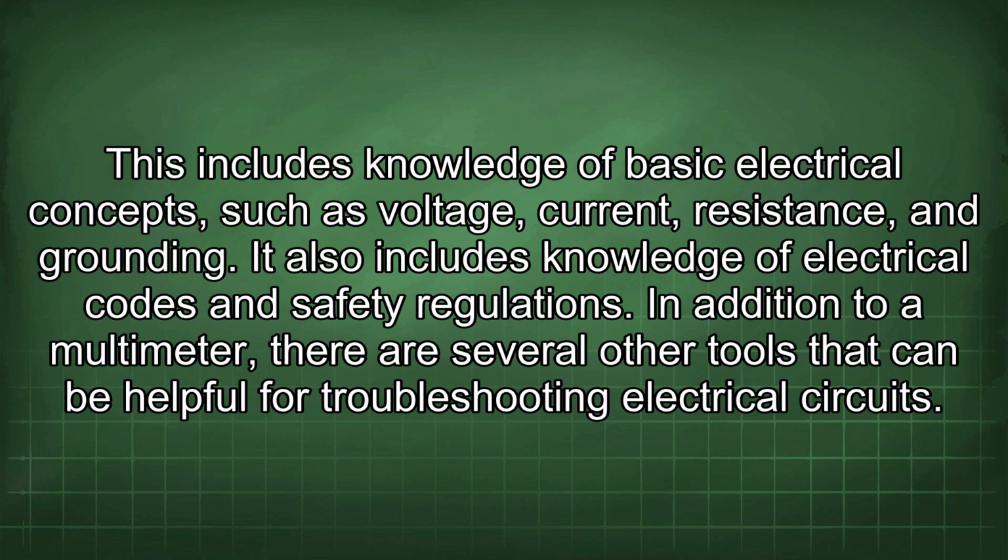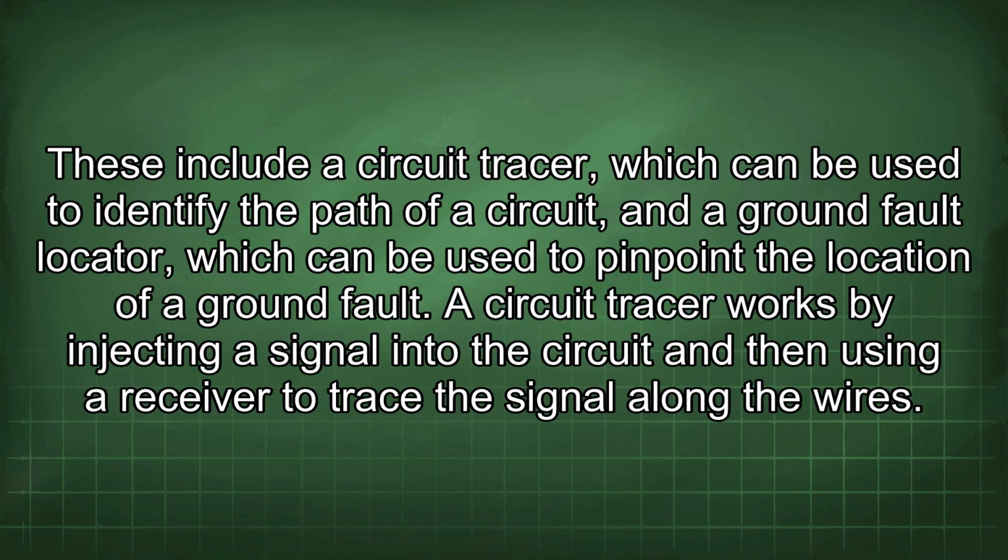In addition to a multimeter, there are several other tools that can be helpful for troubleshooting electrical circuits. These include a circuit tracer, which can be used to identify the path of a circuit, and a ground fault locator, which can be used to pinpoint the location of a ground fault.